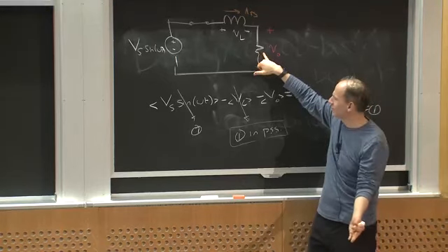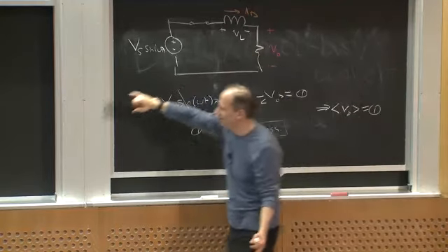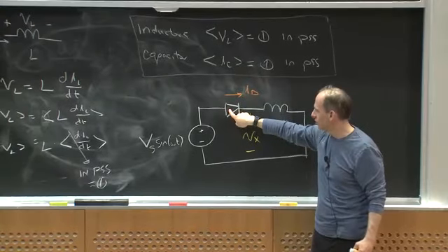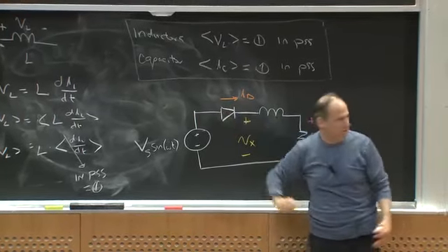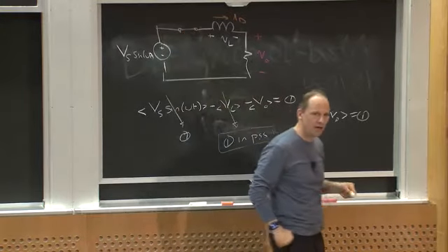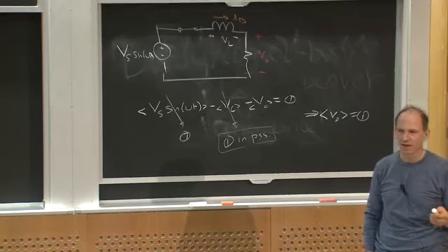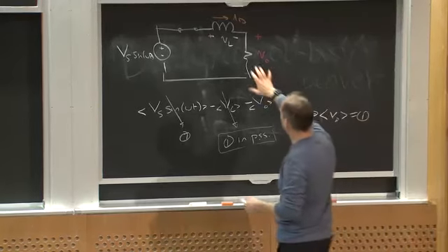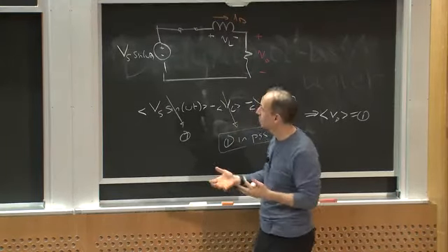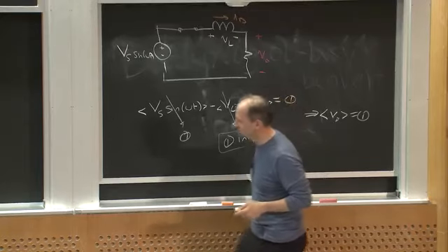And if the voltage across the resistor is negative some of the time, the current through the resistor is negative some of the time. But we already said this diode can never have a negative current, right? So clearly my assumption was bad. When I assumed that this diode was turned on, that might be true for some time, but it can't be true all the time. So my quest to use this inductor to filter the waveforms maybe can't work out, or at least as I've done it so far. What would I get for waveforms if I did this?